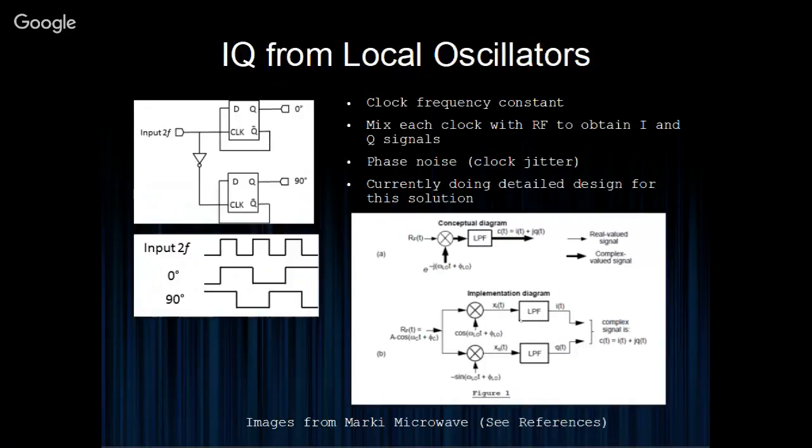I'd just like to point out at this point that when you're mixing and down converting, you end up with a lot of harmonic content. So the idea of these low-pass filters is to remove anything above baseband that isn't the modulated carrier. So you're talking about harmonics, either harmonics from the clock input, which is quite relevant in the use of digital logic for driving oscillators, and also the higher order harmonics as a result of passing through the nonlinear elements of the mixer.